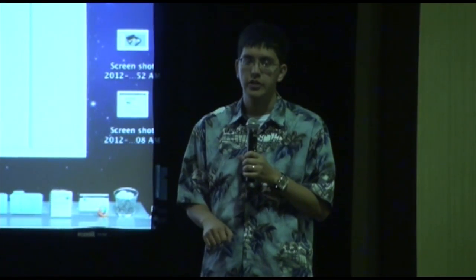The question was whether you can change the URDF dynamically if, say, you either attach something or there's damage to your robot, like you mentioned. Currently, you could reload the URDF parameter into the parameter server, but then you'd have to make some functionality for whatever uses that model to reload the model. So currently, I don't believe there's any particularly good way to do that. So yeah, as Jan said, there are ways to attach objects with planning.